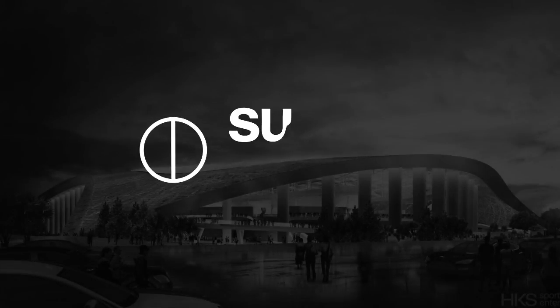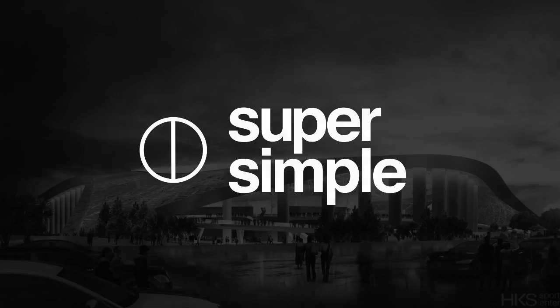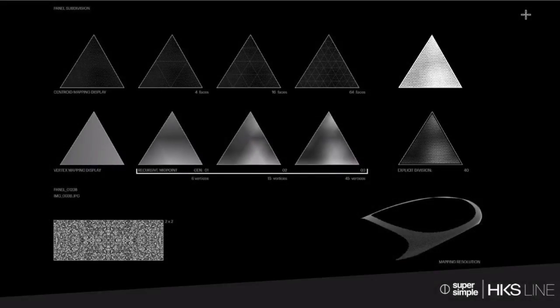And so moving through here, we're just going to flip through these to see the progression, but I just wanted to give you a sense of looking at the panel subdivisions. We're subdividing each of these triangular panels, but we're also looking at how we're tiling the overall image by the same token. So across the upper image that you see there, we start with the triangle and we start to subdivide that to different degrees, and that allows us to really keep the perforation patterning aligned with the panel. And then we're looking at the vertex mapping, where we're starting to use that to create some of the falloff between our solid and void.